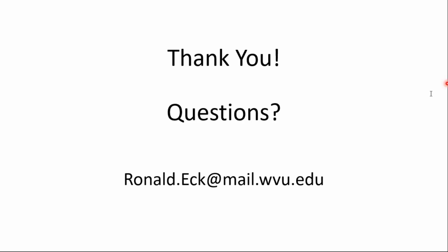Great question. And again, I'm sorry I have to give the same answer. I'll say it depends. For example, it might depend on whether that corner that doesn't have a par or a sidewalk is in the plan somewhere. Maybe something is actually planned that within the foreseeable future there will be a subdivision on the other side of the street or a retail development that will have sidewalks. I would say in that case, you probably should go ahead and put the curb ramp and detectable warning on the other side of the street.